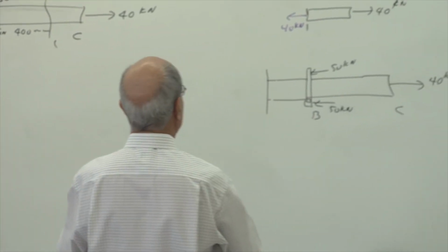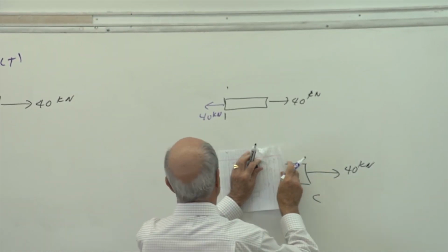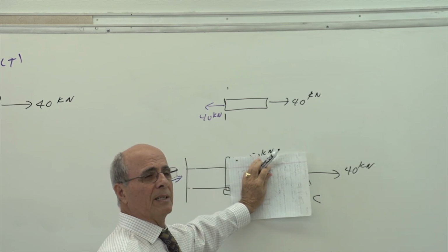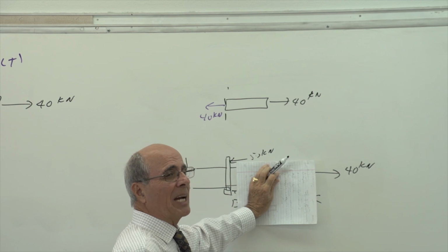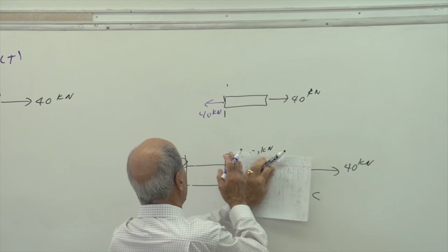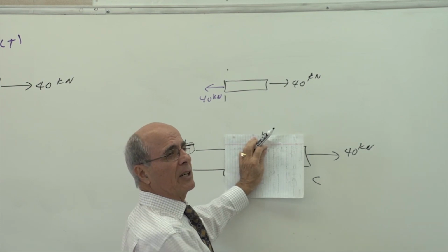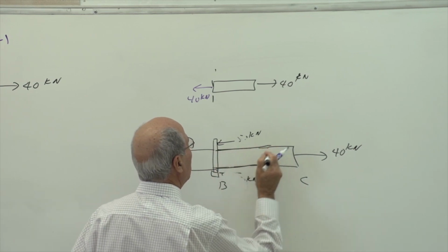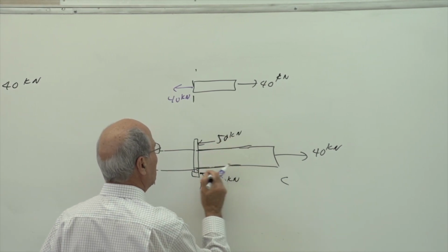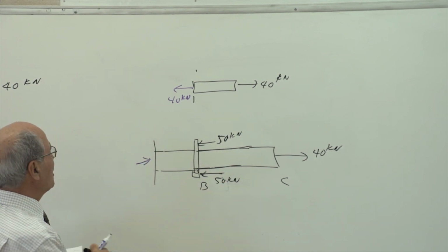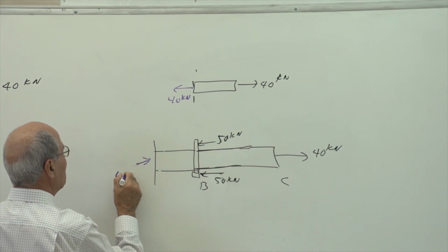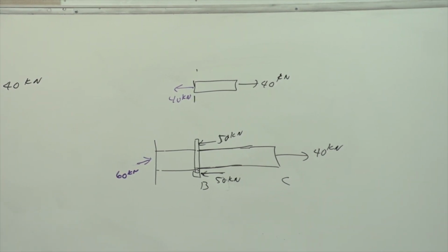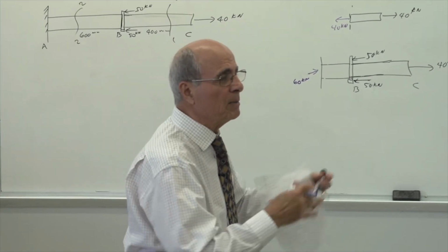But 60 going to the right, what does it mean? Forget about that now. Here, cover this. If I put this force here, is it under tension, am I pushing it or am I pulling it? Pushing it. Everybody see that? Right now, if this was fixed, you are compressing this. Is that correct or not? Oh, sorry, I ruined my picture. So, first, is that understood? Correct? So this is right now internally 60 kilonewton, not 100 kilonewton, and it is in compression. That means member AB gets shorter, member BC gets longer.